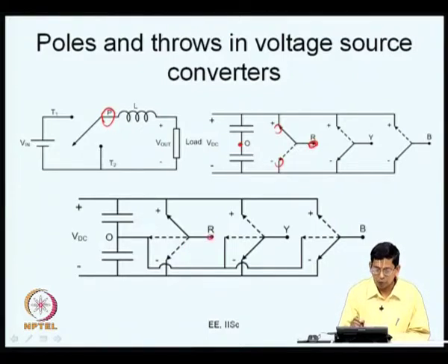you have this pole connected to any of the 3 throws now. So, what you have is the time average of all the 3 voltages. Typically, in a switching interval you might not connect this pole to all the 3 throws, you might connect only to 2 of the throws, maybe to plus and 0 or 0 and minus, and you will get an average which is either between plus VDC by 2 and 0 or 0 and minus VDC by 2 at this potential now.